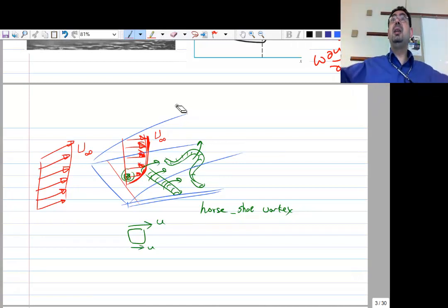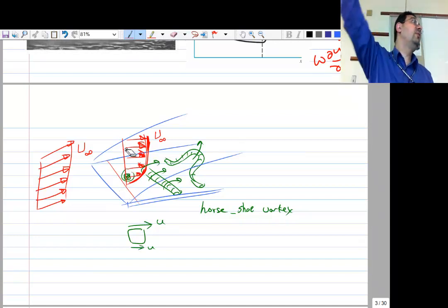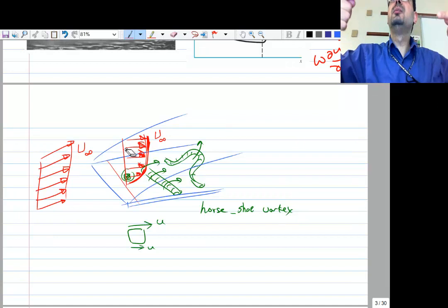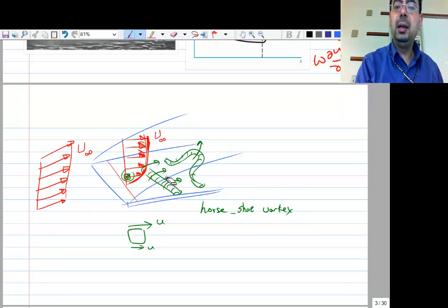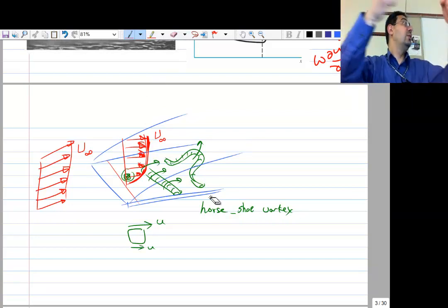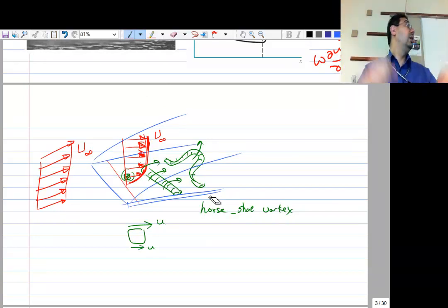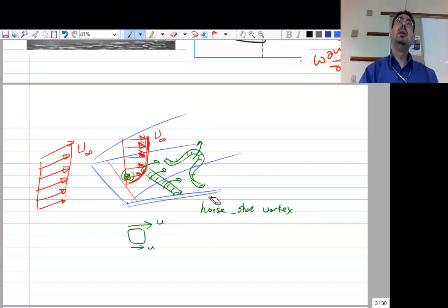And so you can see this roll of circulation being created because, again, of the velocity gradient near the wall: this fluid particle is trapped by the wall and the one on top of it is moving faster than it, so it tends to rotate, right? And so that sheet gets a lifting force that pulls it up, and it forms this horseshoe vortex. It's a vortex, a filament of rotation, shaped like a horseshoe. And then it just breaks into the flow, and you have all that chaos being created.